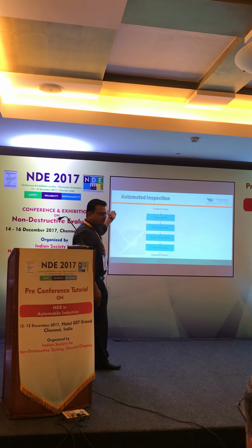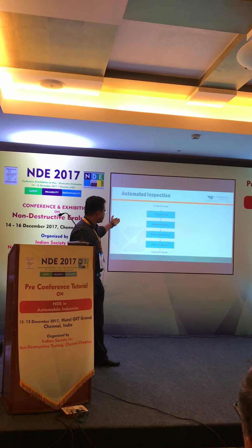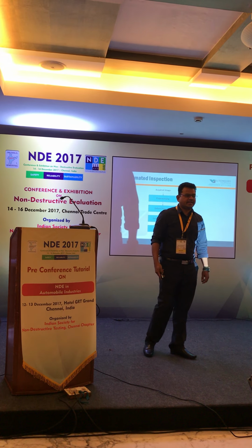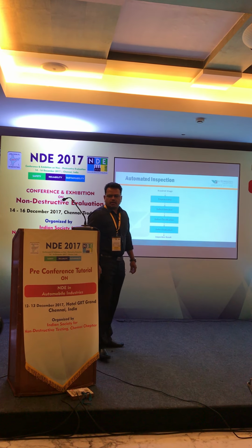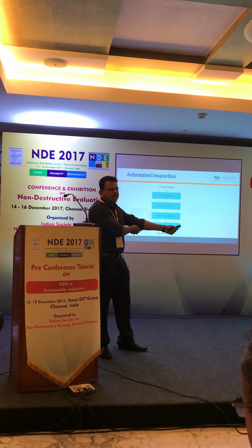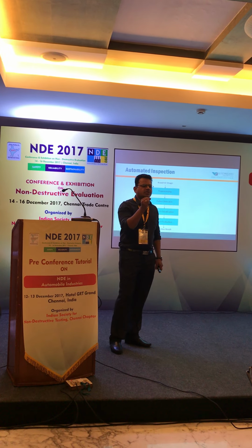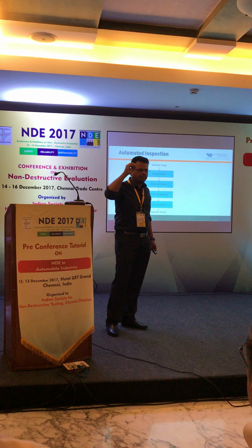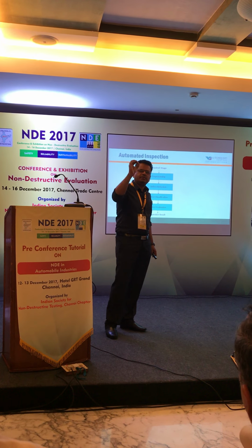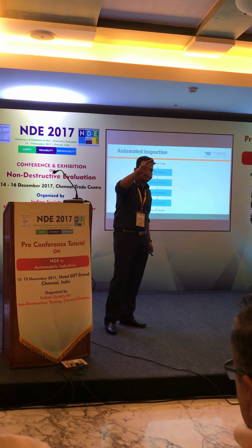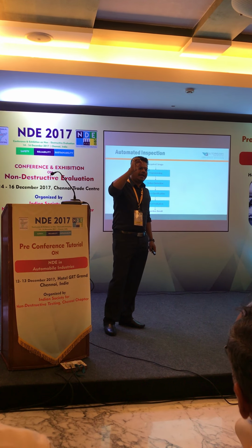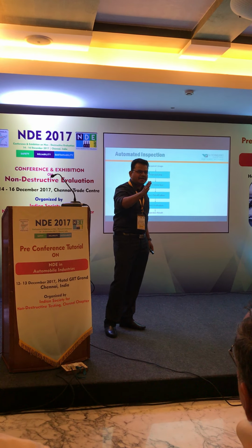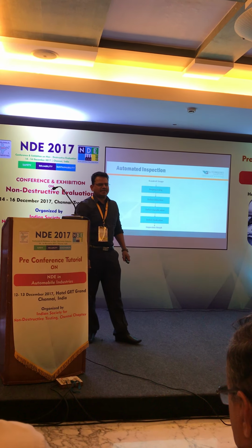As I told you, the acquired image, the processing, the defect detection, the defect classification, even the classification: it's a level 2, level 3, level 4. The phenomenal thing of an ADR is that we can have a region of interest. The customer says, I'm not much worried about this region. My more sensitive region of interest is this. Here, a level 2 needs to be accepted, and a level 3 defect needs to be rejected.